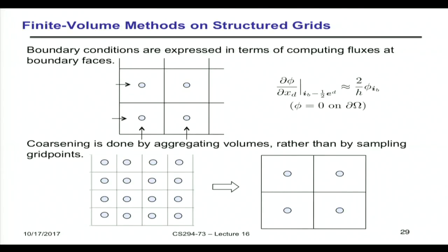For example, if we were going to calculate the distance between this cell center of our finite volume and a boundary where we were trying to enforce a homogeneous Dirichlet boundary condition, we could do something simple, which is basically say delta phi goes from 0 to the value in that cell, and then delta x is half a grid cell width. So I'm going to approximate my gradient with this. It looks like a gradient from 0, but only over half the distance, so it's twice as big. That would be one way that you'd see a different operator for finite volume than finite difference.